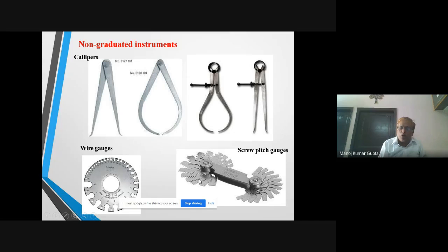If there is a bolt with threads, then we can check the threads with the help of these leaves, for example M20, M6, M8, or M30, M40, etc. And pitch is also sometimes written on these leaves: 3 millimeter, 4 millimeter, 5, 6, etc. On the leaves, the value of the metric thread is written, and pitch is sometimes written.